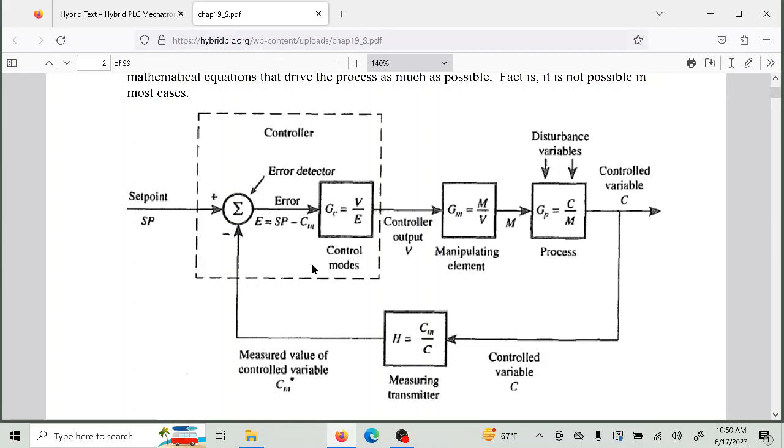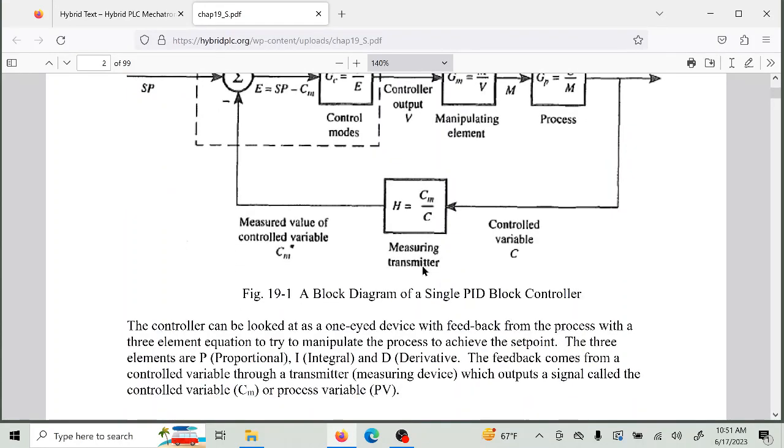Now, the old-time PID controllers were continuous. Today, we settle for something that's not continuous, but is run on a clock, either every so many milliseconds or every so many seconds. So basically, we run it at discrete intervals. Whether it is continuous or on a clock, it usually doesn't matter, but again, we are compromising by using a digital system instead of an analog system. Now, the example I'm going to show you right below this is an analog system because it's continuous, and I'm going to show you this in a second.